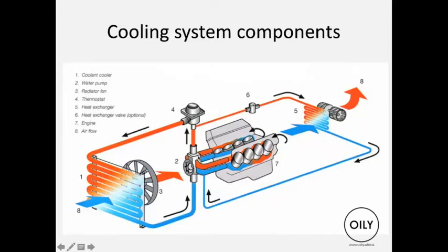So the coolant must be compatible with all of those components and be able to transfer the heat from the engine to the radiator, where it's just lost as heat to the environment. And of course, it must lubricate the pump and mustn't cause rusting; it must protect all the surfaces against rusting and all that sort of thing.